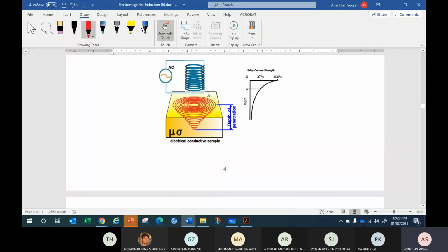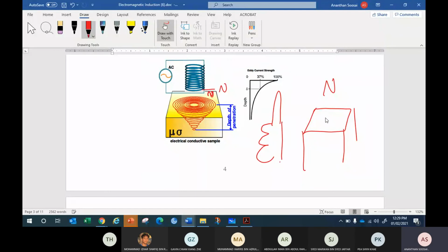Okay, so when the bottom of this electromagnet induces north, the conductor on top will try to induce what pole? It will try to induce north, because you want to oppose the change, right? Lenz's law. So you have a conductor like this, and you want to create a north on top. How should the current flow in this conductor? Like a right-hand grip rule. Should the current flow clockwise or anti-clockwise to produce a north pole on top?